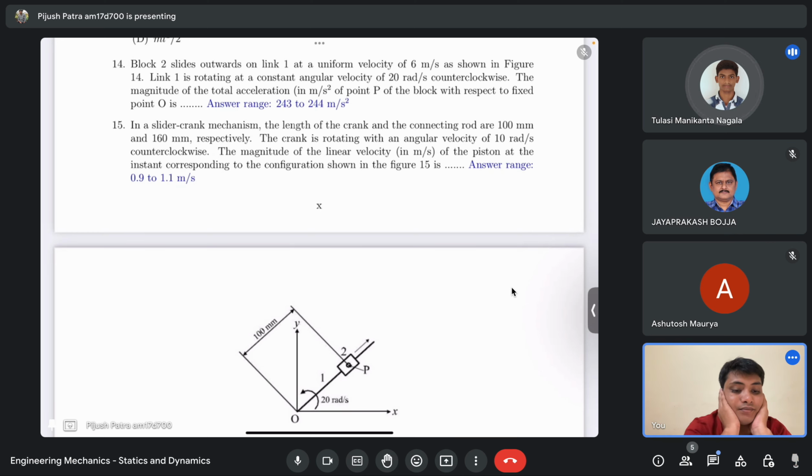Yeah, you are right. You assume it is counterclockwise. Omega k cross i gives j, and k cross j gives minus i. Omega is equal to some omega naught into k cap, and r is equal to, let's say, x i plus y j. Can you do that cross product and tell me the direction?